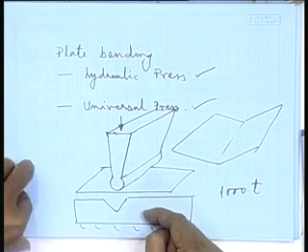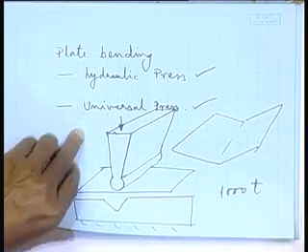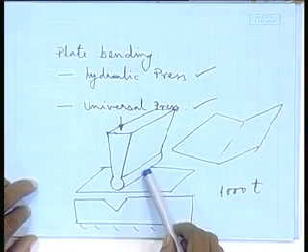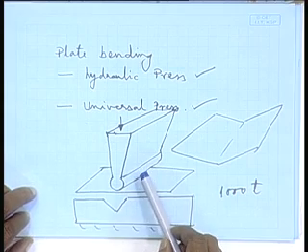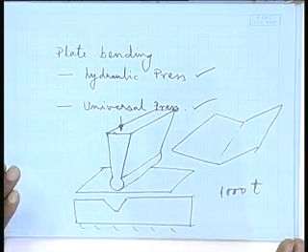So what is the other way of avoiding those things? One possible way is making something called a universal press, because here you see it's also a kind of universal hydraulic press, but here I won't say universal, I am just naming it hydraulic press because it's only capable of making V kind of bend shapes. Only thing, with my skill I make this V, then turn it, put a stroke here, so I bend this side up and so on and so forth. That's how I get a smooth curvature, right?